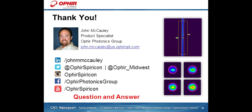Looking down here, thank you. So ellipticity and circularity are the same even though they sound like opposite definitions. Ratio equals 1 is perfect. That's correct. A 100% measurement of circularity and ellipticity, those are effectively the two very common terms. They effectively mean the same thing. Ratio equals 1 is a perfectly round beam. Yes, you are correct. So anything less than 1 is going to tell you how round or how circular your beam is.